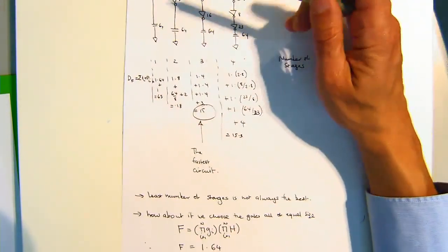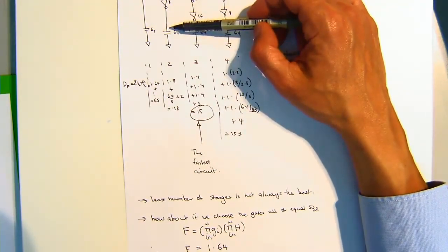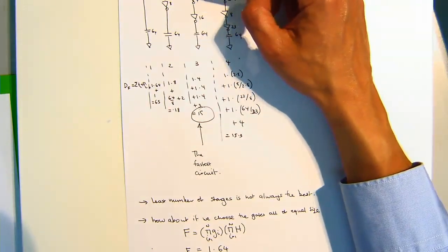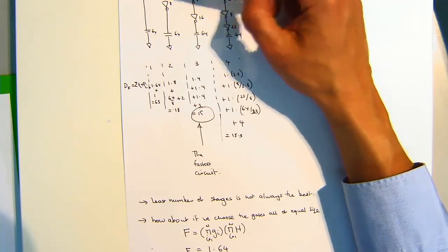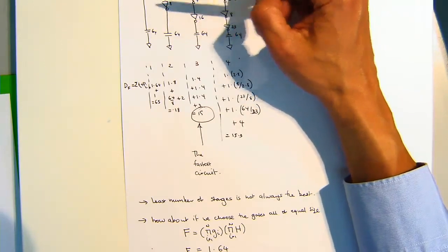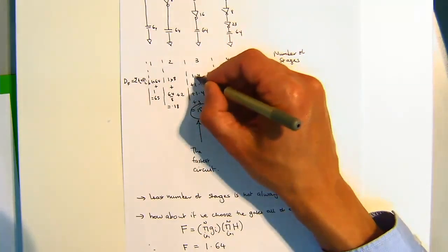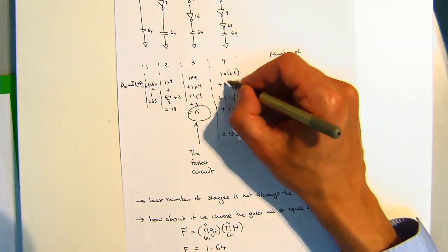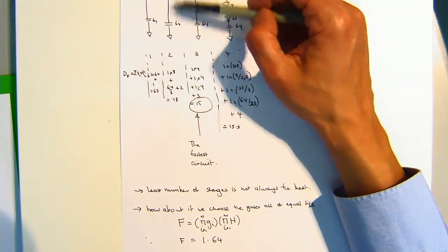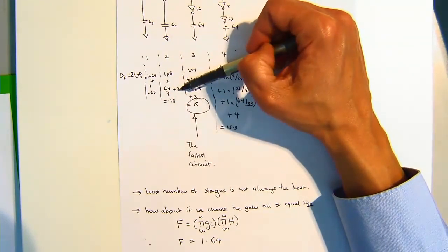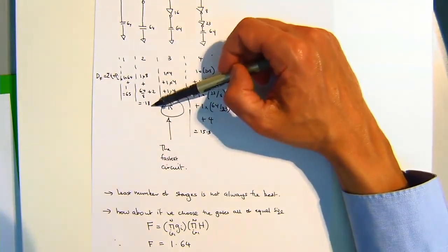Okay, let's look at circuit number 2. What's Hi here? 8. And here, again? 8. So therefore we've got 1 times 8. And these are times, so even though I've got dots, I actually mean multiplication. And here we've got 64 and 8. Where does the 2 come from? 2 parasitic delays. Okay, so therefore the delay here is 18 units.